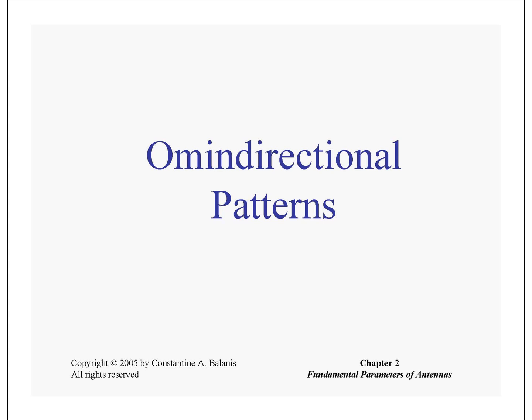Now let us come to the omnidirectional pattern. What is an omnidirectional pattern? It is a pattern for which the directivity or gain in one plane is omni, that is, equal in all directions. However, in the orthogonal plane, the pattern is not omni, it is directional. The general mathematical form of the omnidirectional pattern is a sine pattern: sine theta, sine square theta, sine cube theta, etc. Mostly the omnidirectional antennas are dipoles and monopoles.